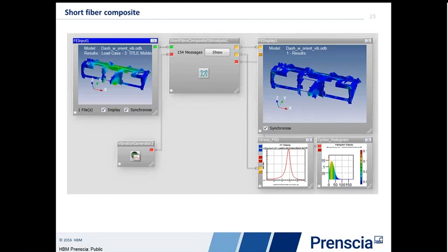So this is basically a process where we've brought in a model out of finite elements that basically the input information in terms of material properties and orientation actually came from Moldex3D in this case. We use exactly that same information in terms of fiber orientations in the fatigue analysis and applied to that a material that was a nylon glass-filled polymer. We're able to go in and apply the PSD loading to the dashboard here.